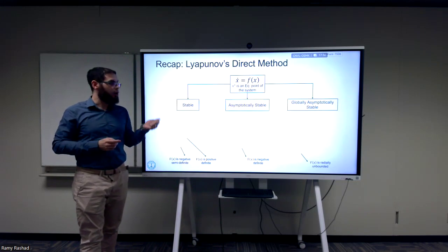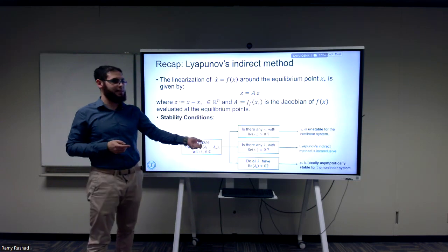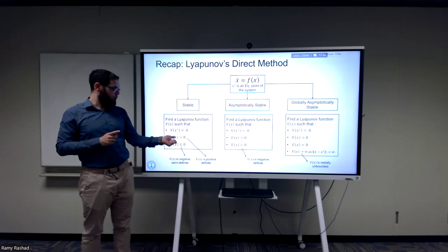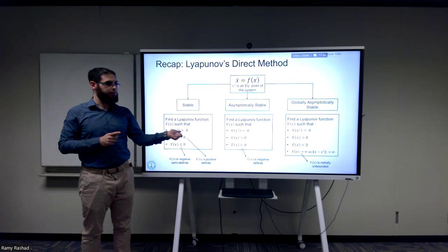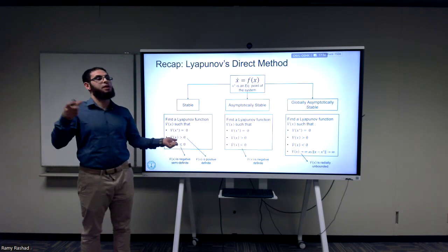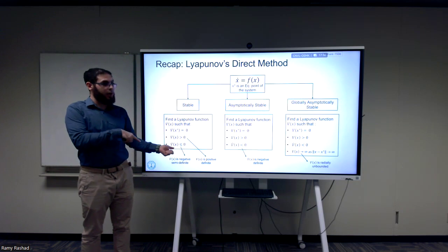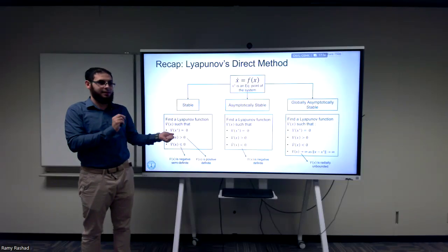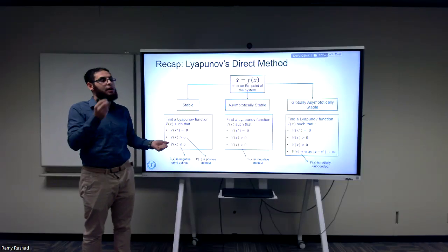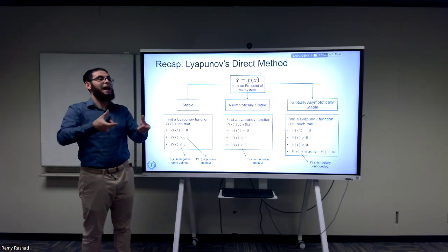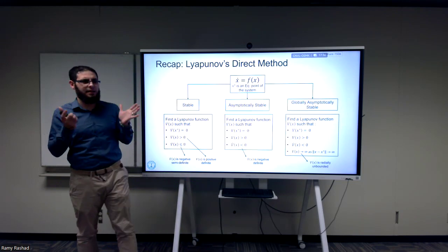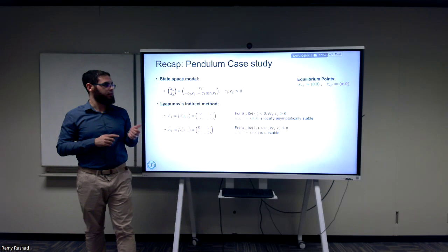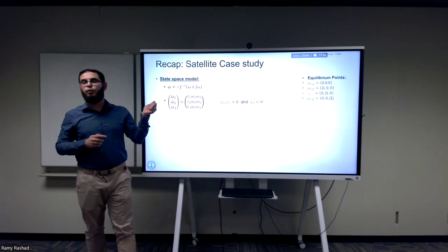This is the easiest way. There are also more fancy ways that you can try to prove instability. Theoretically, if you can find the Lyapunov function where v is 0 at this point, and v is positive around, so it's positive definite, and you can show that v dot is also positive definite, you can conclude by Lyapunov's theory that it's unstable. However, it's very hard to find this Lyapunov function that it's positive and also its v dot is positive. So it's not even used in practice.